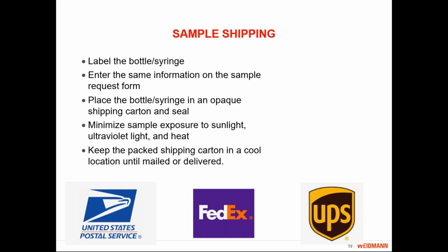All of us in the industry recognize that some older transformers do not have a year of manufacture stamped on the nameplate. And depending on what kind of transformer owner or user you are, you may or may not have good records of when that transformer was purchased. So you may not always be able to identify that year of manufacture, but do make an effort to do that, because it does help us interpret especially your DGA information a little more accurately than if we don't know what that transformer year of manufacture is. So all that information goes on the sample request form.